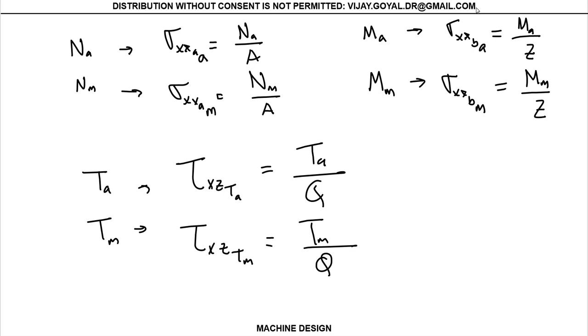So what you're going to do in the problem is take your problem and say, I'm going to build two stress states. One is alternate, sigma XXA, and you have to know what your critical location is. So you always have to start with your static analysis, okay?